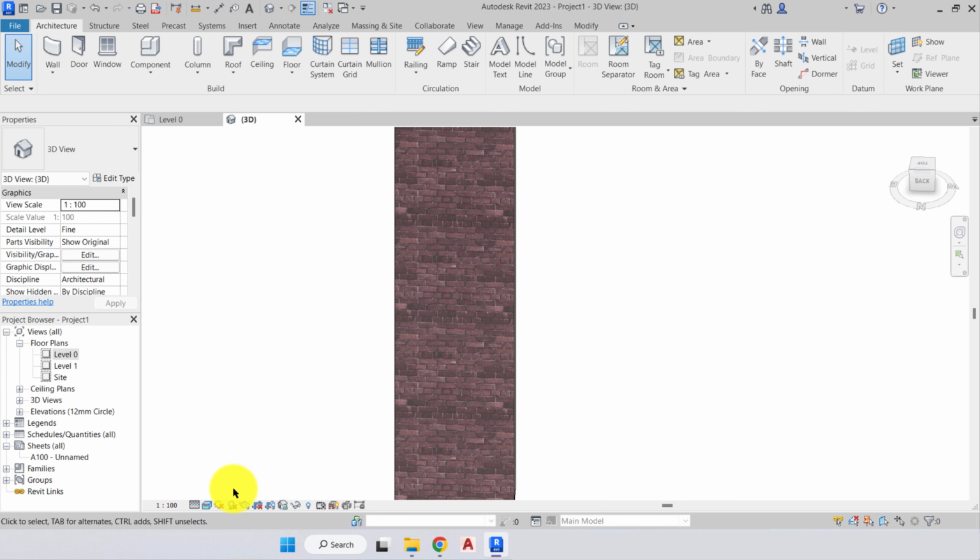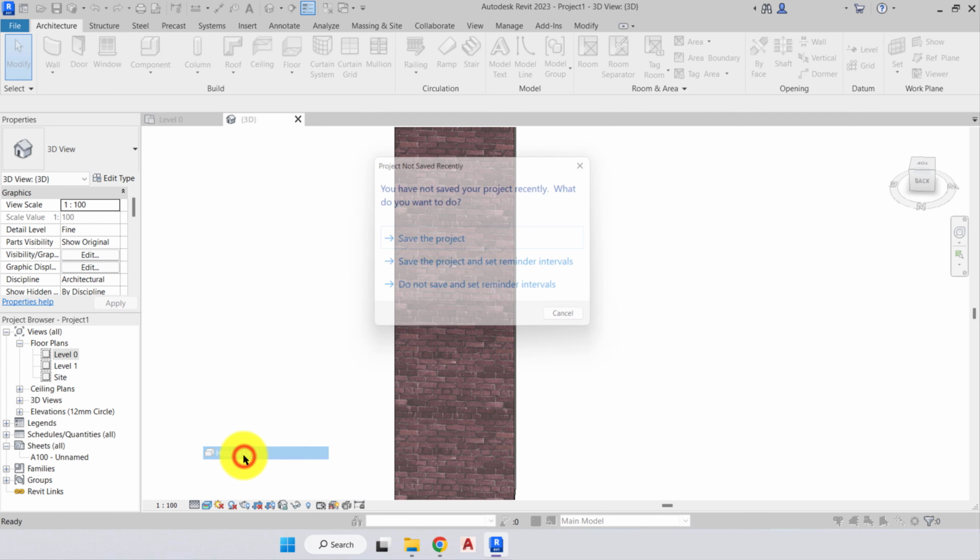So when we're modeling, we tend not to use realistic at this stage. The reason being is it's showing a real image, so your computer will be constantly trying to render that image, which will slow down your progress, and the computer will be working overtime constantly to try and keep up. So your model will become laggy. Yes, it does look great, but we want to be able to model quickly and efficiently. So to do that, I'll always use the hidden line.